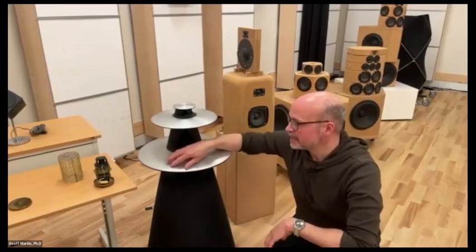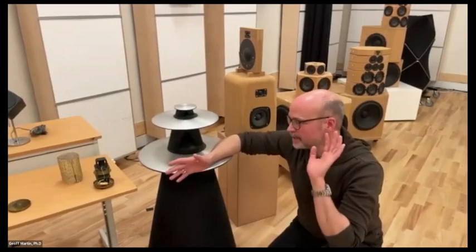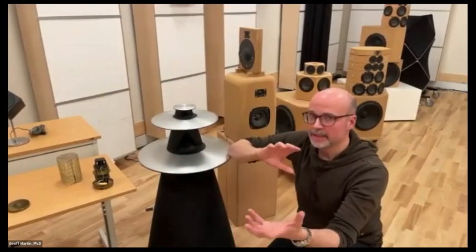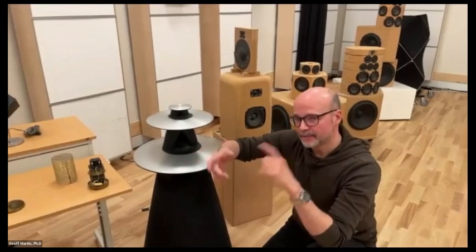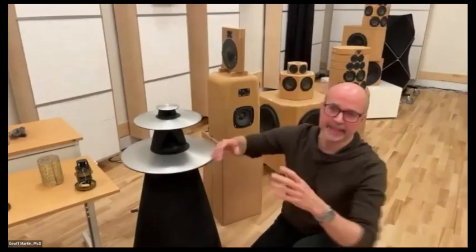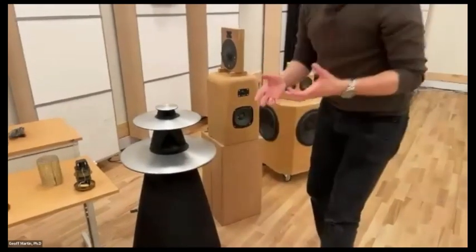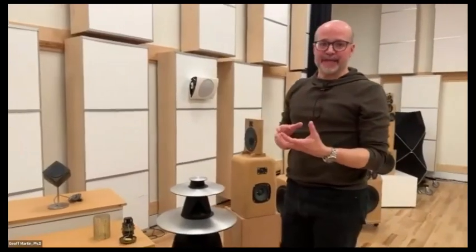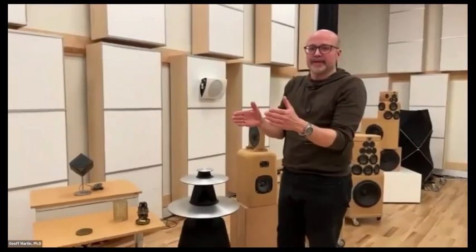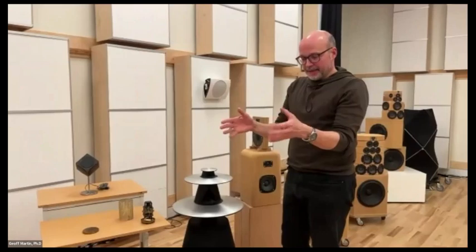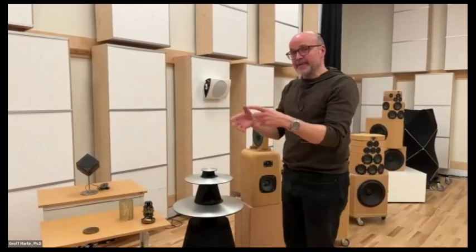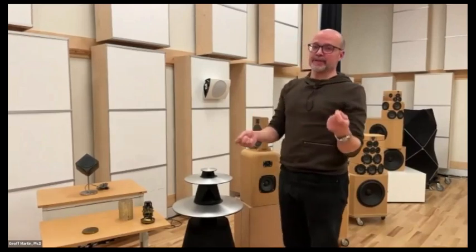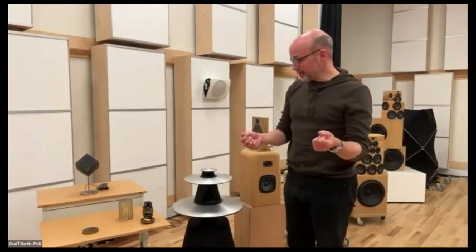The other advantage of making a speaker that has a wide horizontal dispersion is that your power response, which is the three-dimensional radiation of the speaker, starts to approach your frequency response or your on-axis response. In a perfectly omnidirectional loudspeaker, then the on-axis response and the power response are the same thing. And the more directive your loudspeaker and the more directional the pattern is with a frequency-dependent directional behavior, then the less your power response and your on-axis response match each other.